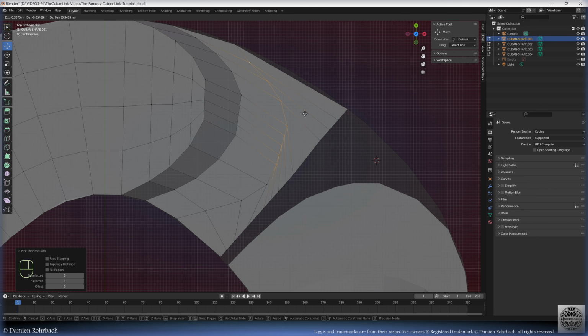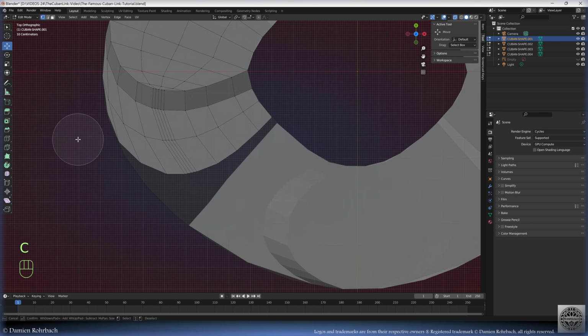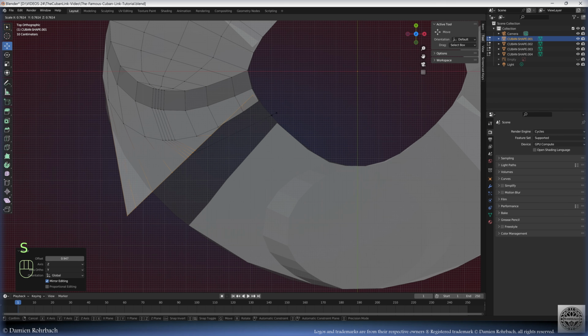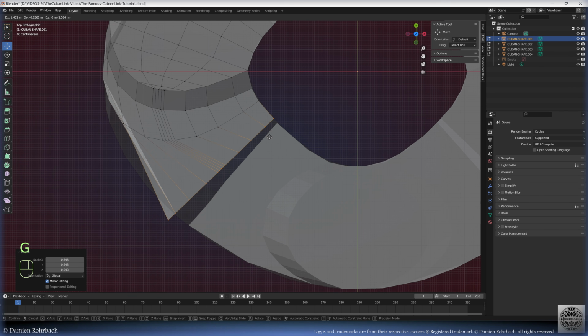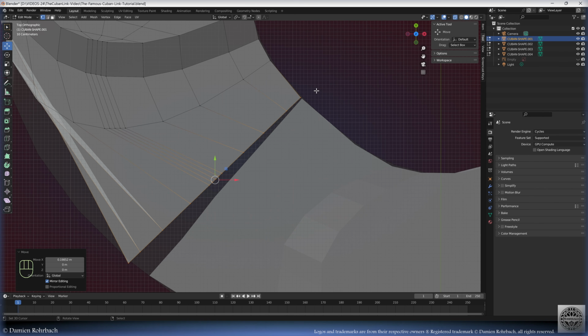Adapt this other level if necessary so your faces are not collapsing. Now go to the other side, select these vertices here, do an S Y 0, shear it here. Now scale and adapt. You can see the position that you have to reach from the other side thanks to the linked copy. This is the cleverness of this method.